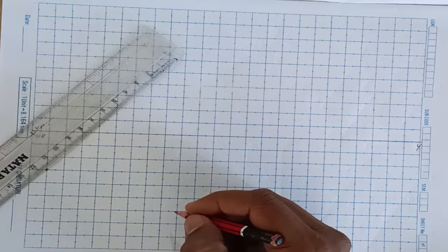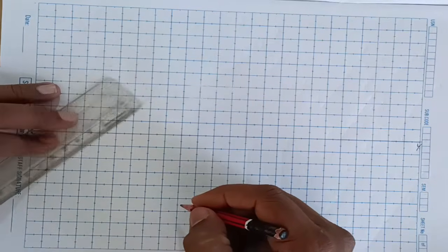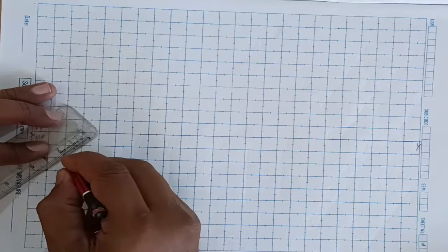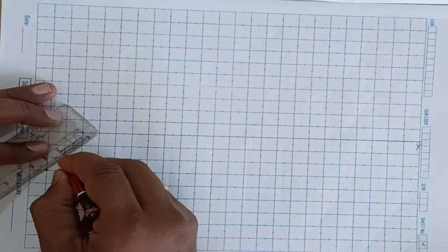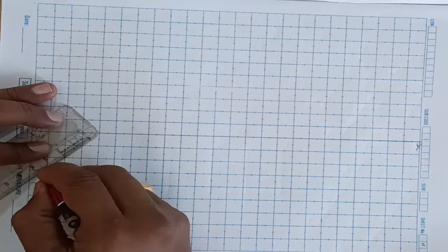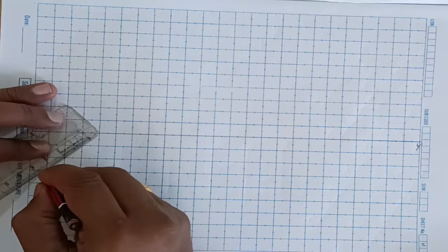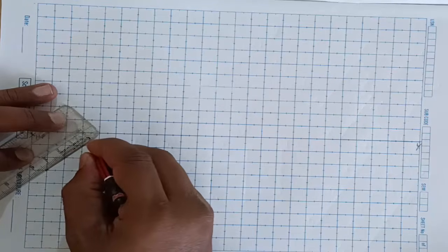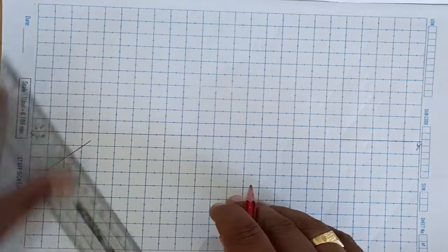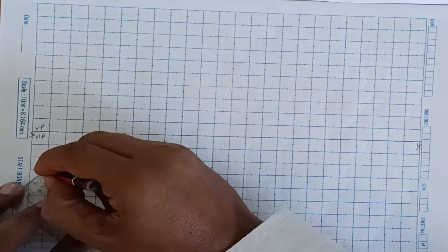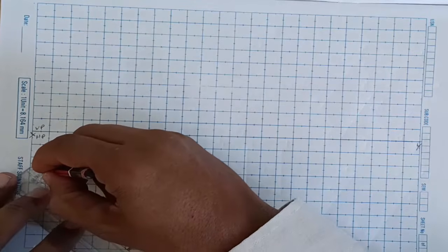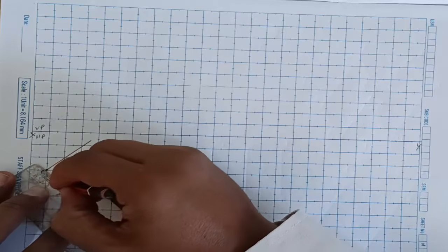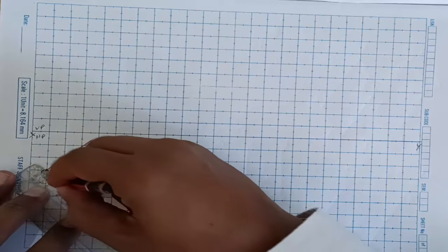The side length they given is 35, so keep the scale. The 45 degree you can measure using a protractor, or else 45 degree means if you take the opposite corner passing through the resting corner, it will become 45 degree only. So I measure 35 here. From this point we draw a line with 35 mm, one side. Same way this side also. Take the reference point and opposite corner, and passing through this one draw the 35.